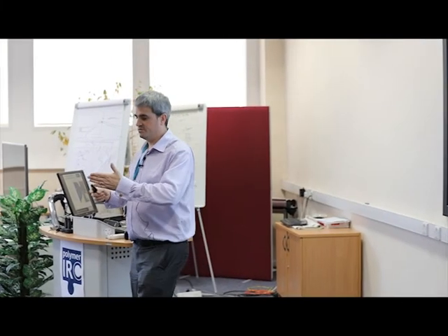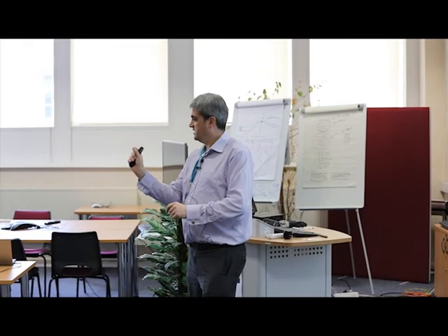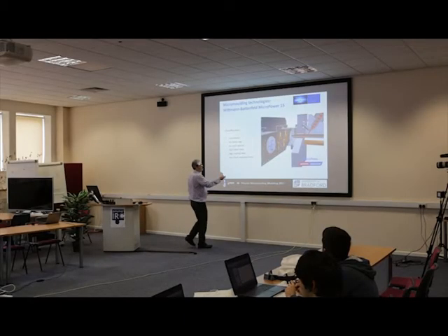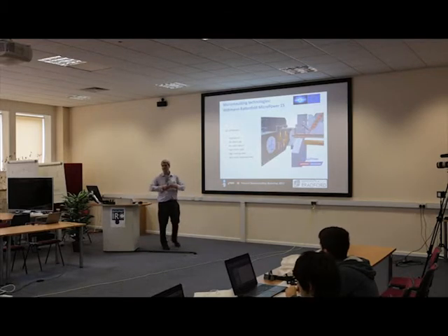In a conventional injection molding machine, you've got this constant contact between the hot nozzle and the cold mold, so you've got a bit of a pressure gradient in there. So the first shot of your next cycle, or the first part of that shot, will actually be a little bit cooler than the rest of the material behind it, and that can cause problems with micro-injection molding. And the last thing is, in micromolding, we're not really waiting for things to cool. These things cool in fractions of a second. So a huge part of the cycle time in conventional injection molding is kind of irrelevant for micromolding.